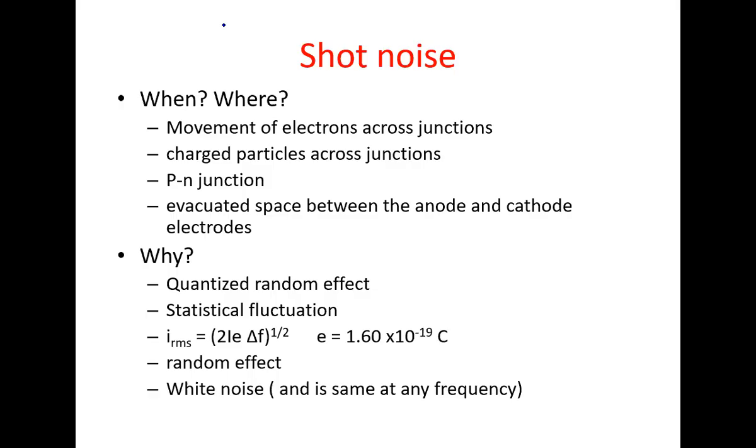You know the formula and you know when thermal noise occurs. You know you can decrease thermal noise by playing around with the formula. Remember, the RMS thermal noise is equal to the square root of 4kTRΔf. So if you want to decrease thermal noise, you play around with the resistor, you play around with the bandwidth. What else do you play with?